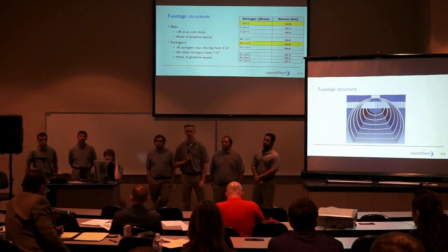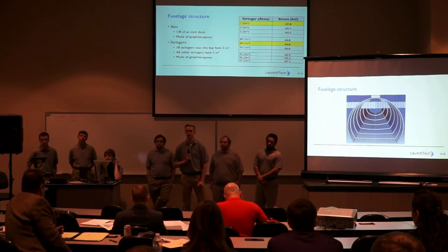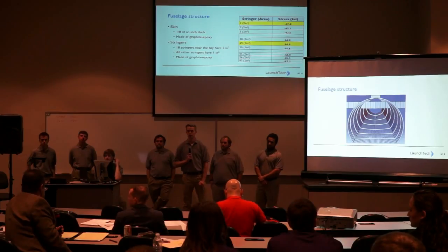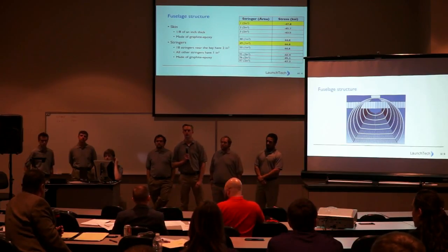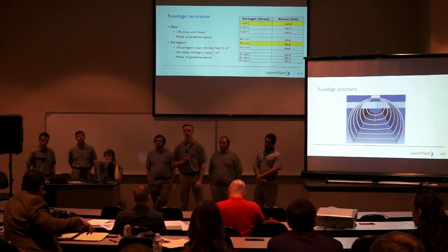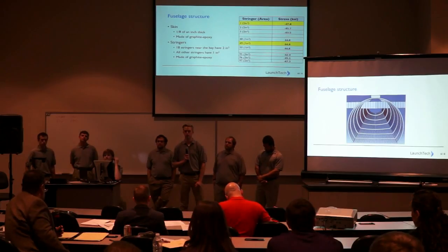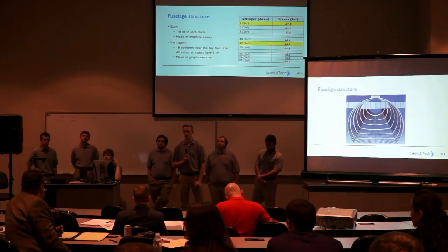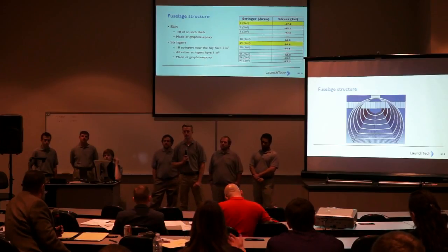One of the things I would love to have seen in this presentation, you are fixing to go to detail. I would love to have seen some conceptual presentation on what your wind tunnel model is going to look like. All I was able to infer from what you said was that you were going to look at the thing with the payload up and payload down and the drag comparison. There are other aspects of this model that need to be looked at in the tunnel, especially the location of the horizontal tail, the effectiveness of those winglets. Would be nice things to know.